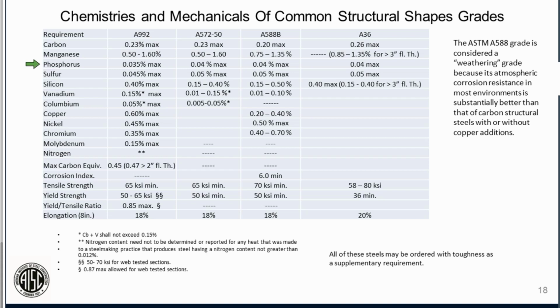If you look at sulfur here, same thing with 992. It's a lower sulfur. That's done intentionally to help the properties of steel, especially Charpy V-notch. And then 572 or .050, .05 max. So those aren't added. Those are residual. We try to minimize those in our processing.